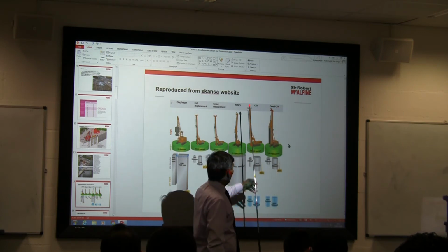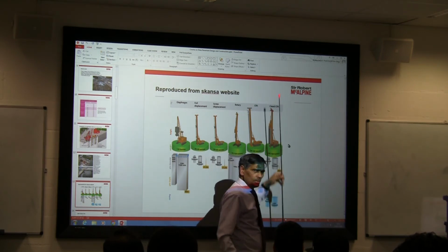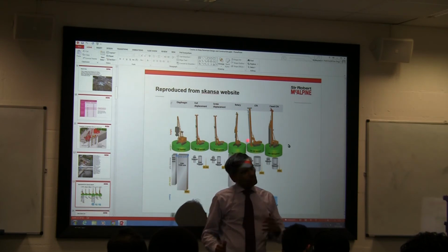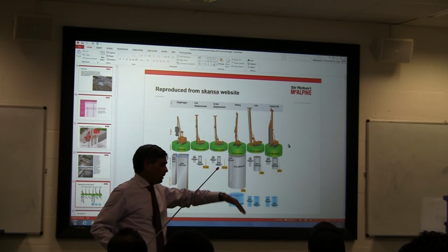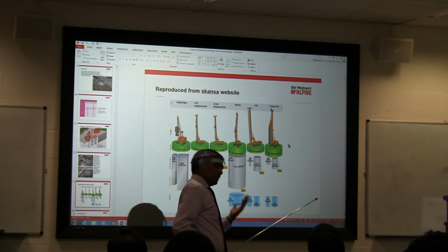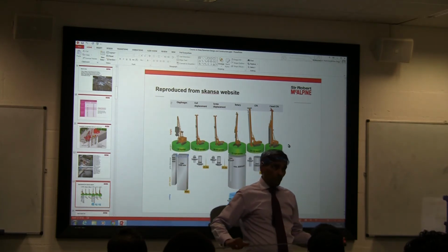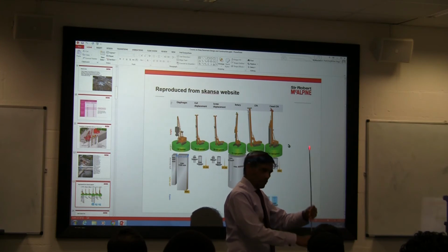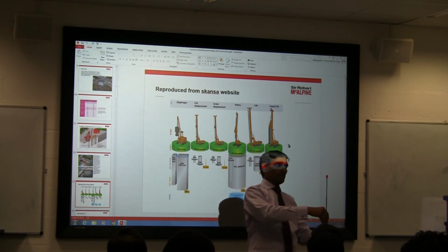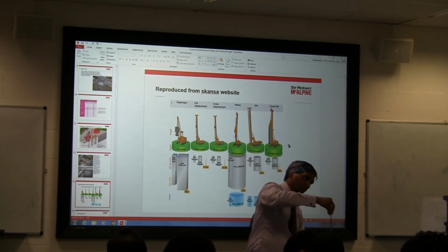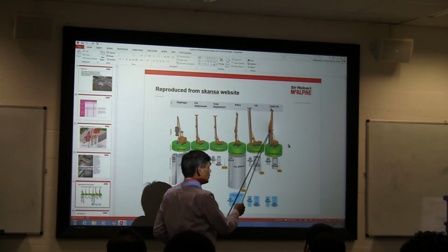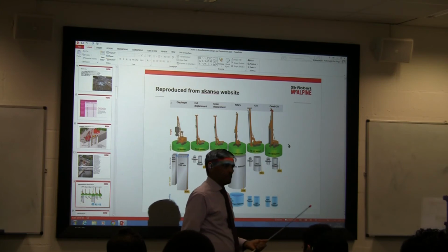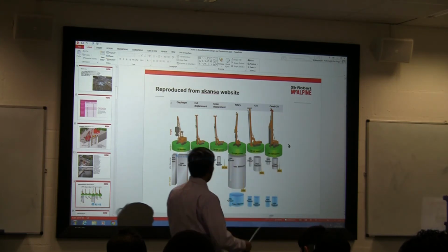Again, you have to think about the headroom heights. Remember, we have a 26 meter auger standing there, so you need enough headroom. Sometimes we came up with low headroom rigs also. Sometimes we have to work in the basement with 8 meter rigs. There are very expensive rigs that can be brought. So you can attach an 8 meter auger and then put another one and keep going down if you've got low headroom height. But if you've got full headroom, they will bring all 26 meters and start pushing everything. So these are the sort of ranges.